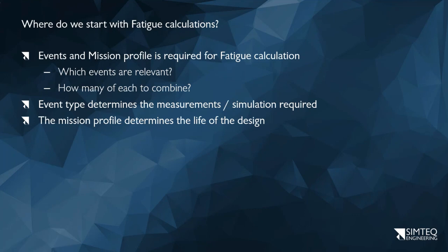Now, a couple of additional examples would be if I design something like a vibrating screen for a mine. In that case, the actual vibration level is reasonably well defined. It's a function of the excitation level and the mass of the structure, which does vary over time, but relatively little.